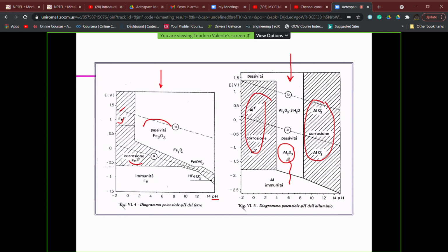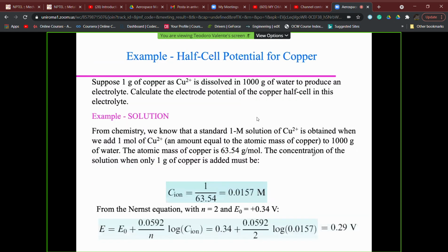If we put our aluminium alloy, or our aluminum in this case, in a too acid environment or a too basic environment, the aluminum oxide on the surface cannot be formed. The ions become stable, and so aluminum can be corroded. And this is also something which fully matches our experience.